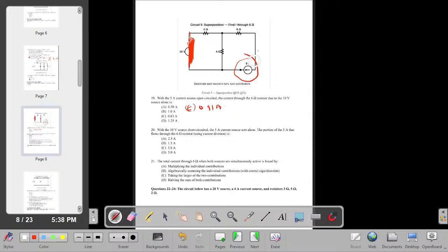And we have this 6 ohm here. So for current division, you have this current arriving here, and it's going to split here. But even with that, there is this 6 ohm here. So I think current division wouldn't work for this particular scenario. Okay. So it's simply the 5 which is arriving here, which is passing through.